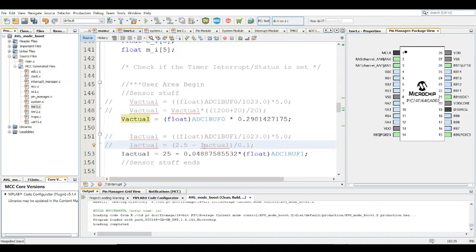You're going to have to say whatever value you get minus 2.5. But I don't like that. I prefer it this way because it's safer essentially. You limit what goes into your microcontroller to 2.5. It's never going to go over 2.5 with this particular situation you have here.